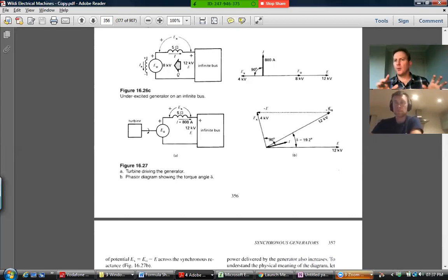And as you play with those two parameters, you can tweak it so that you can almost independently, in a way, adjust the real power and the reactive power. Not entirely independently, but if you play with the two of them in the right amounts, you can actually come to a point where you can supply a chosen amount of reactive power and a chosen amount of real power. And we'll see in our experiment on campus